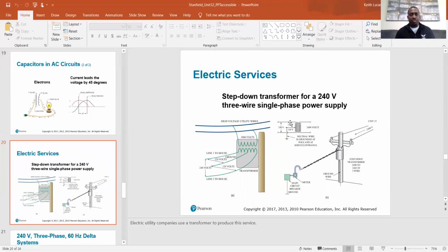You have your operating voltage, which is 120 or 240, depending on what motor's being operated, because that's what it takes to turn that motor. But then you also have your control voltage, which is 24 volts. And that 24 volt signal is coming from the thermostat to the board, from the board to your contactor coil. And again, once that 24 volts comes from your board to your contactor coil, boom, it closes the contacts, and now it allows your operating voltage to flow from here to here and bring your motors on.